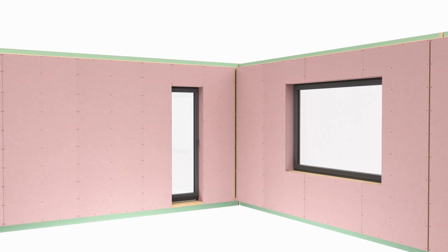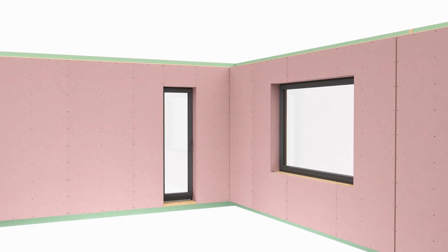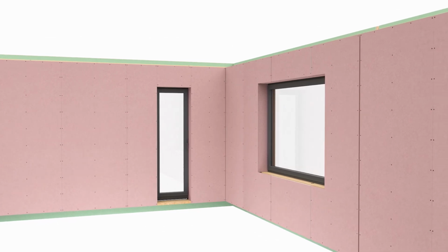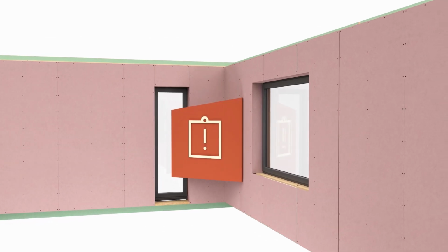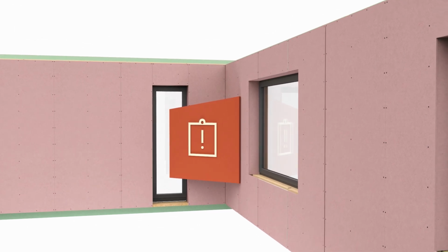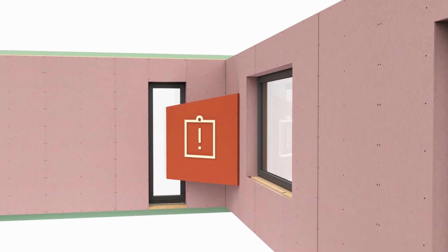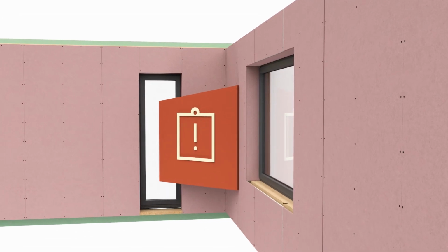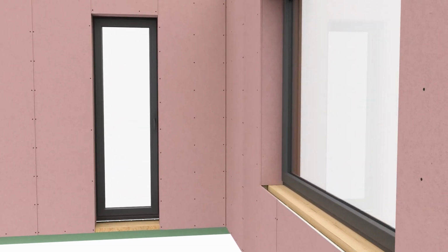Most often, the last work of the erection process is the sealing of the joints between board layers of elements. Here it is necessary to strictly follow the requirements of the project, because in addition to the airtightness requirement, the fire resistance of the joints may also be required. In case of fire resistance requirements, the joints of drywall must be sealed with fire-retardant mastic, for example, acrylic with fire resistance properties. In rarer cases, when the joints turn out to be very large, fire-retardant foam is also used for sealing.